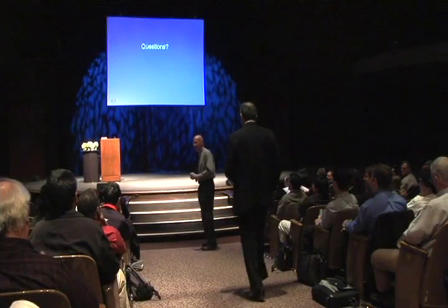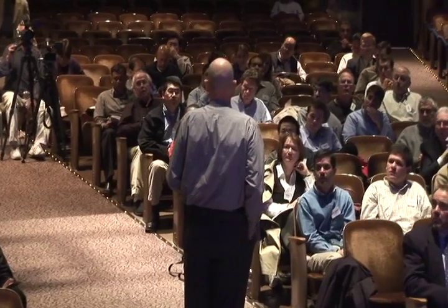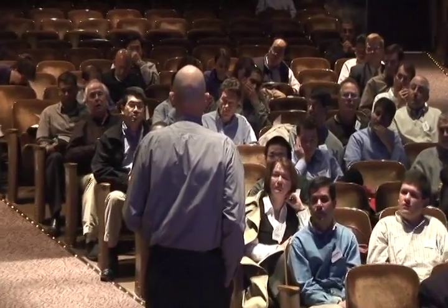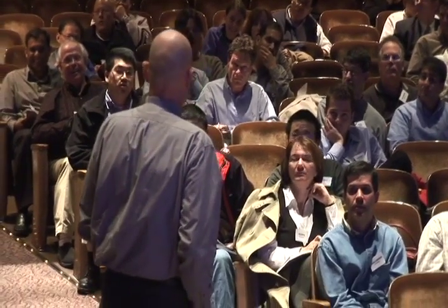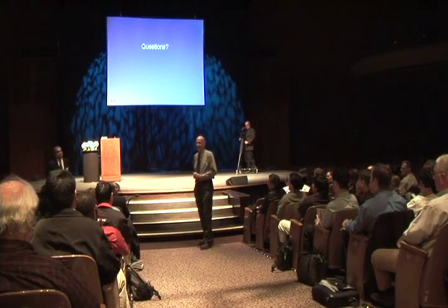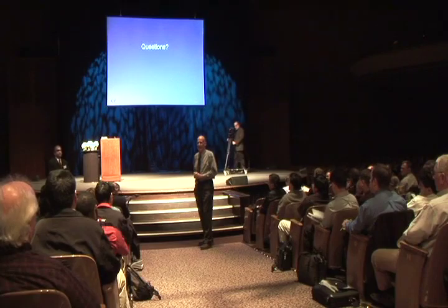Yeah, Dr. Powell. And how to consider the buckle in the column? You mean an actual column or a brace? It's a typical column in a moment resisting frame. Yeah. Well, they don't buckle. I don't think so. The frame as a whole can buckle. It forms plastic hinges and forms a mechanism, and the P-delta effect can cause the frame as a whole to buckle. But I think you'd be pretty hard-pressed to find a column in a moment-resisting frame where the column actually buckles as a pin-ended column.